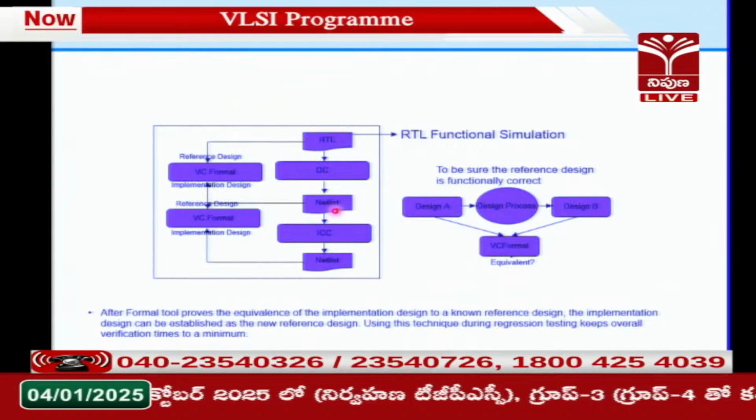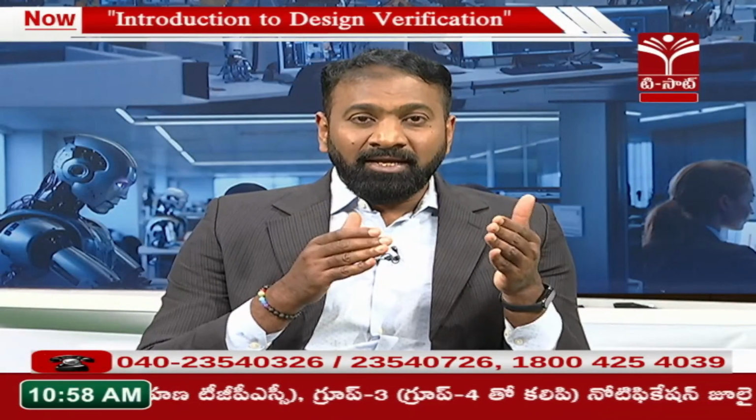Whenever there is a design transformation happening, we have to ensure both the input design and the netlist are equivalent. When we had an adder, the RTL code of the adder could be as simple as: assign sum is equal to A XOR B. That's my adder functionality. The carry will be carry is equal to A AND B.